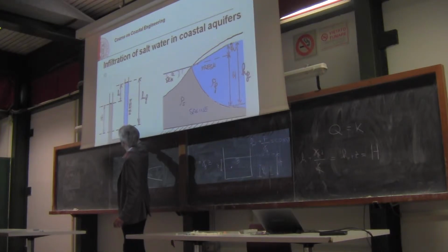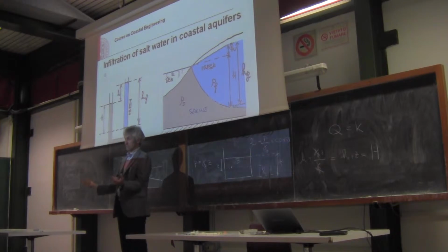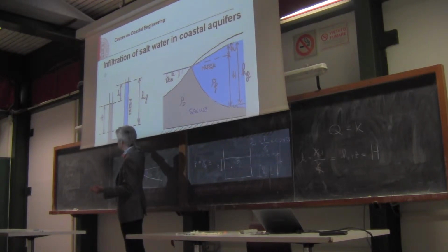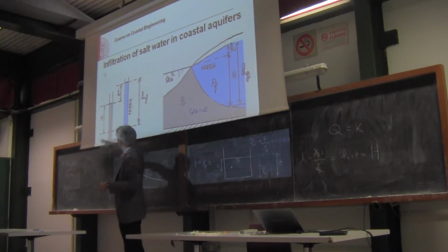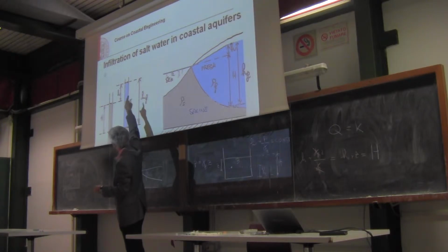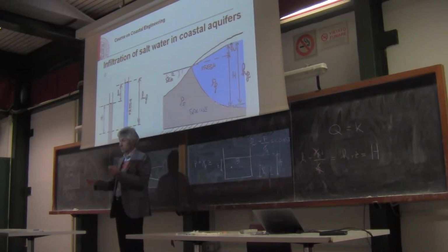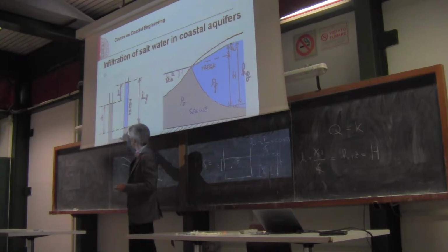If you put in two communicating pipes salt water and fresh water, and you don't have any mixing, you wouldn't see the water at the same level in the communicating pipes. The fresh water level would need to be higher in order to keep the equilibrium here.